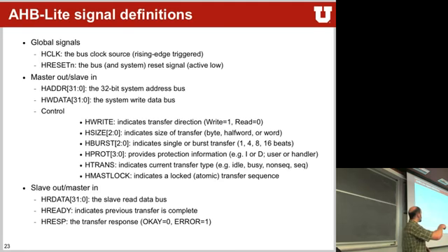We have a burst indicator that tells us how many transfers we want to read. We will look into the burst in detail. So we can increment at a certain number and do a very quick read from a memory location, then increment the reads automatically. You have the protection that we are using. We have the HTRANS, HMASTLOCK. Most of these we will almost never need to worry about.